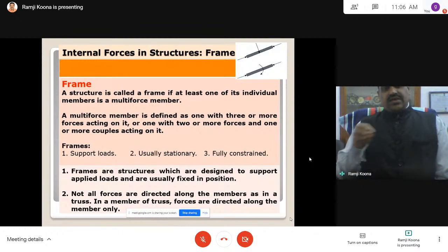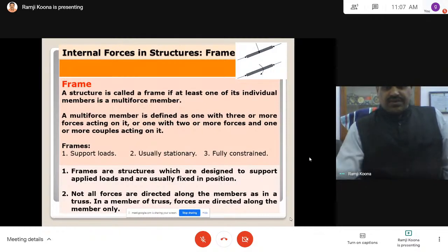So that's why the stiffness matrix, in the case of a bar, where 2 nodes are there, is 2 by 2, because 1 degree of freedom at one node and 1 degree of freedom at the second node. Like that, it depends on how many degrees of freedom you are considering, but here at a single point, in local axis, it has 1 degree of freedom. If it is planar, in global axis, 2 degrees of freedom. That is the resolution of the force. Whereas the beam has 2 degrees of freedom, and the frame has 3 degrees of freedom at a particular point of view.